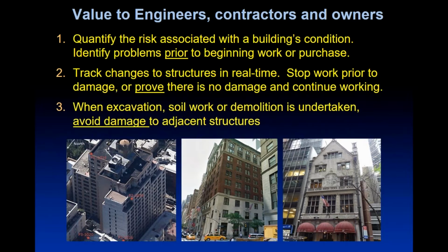Looking at this 3rd building, there is blasting going on across the road. New York City allows you to construct underground and make big caverns by blasting away. Quite naturally, people who are nearby are concerned at what might happen to their structure. And in this case, we were monitoring, again, for a period of about 2 years there. And we monitored the effects of the blasting, the intensity of the vibrations, and the effect on the building. And we're okay going through there.